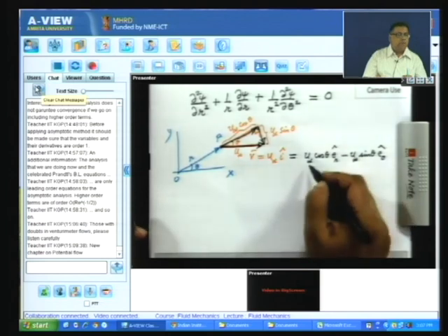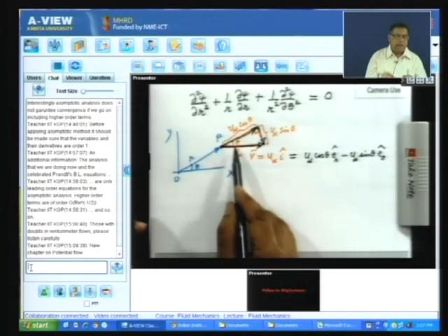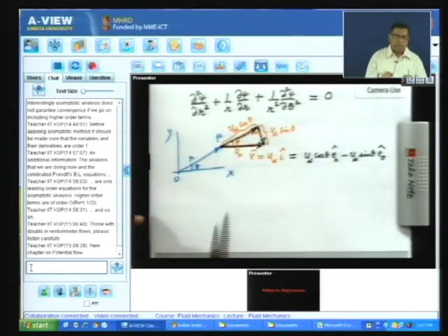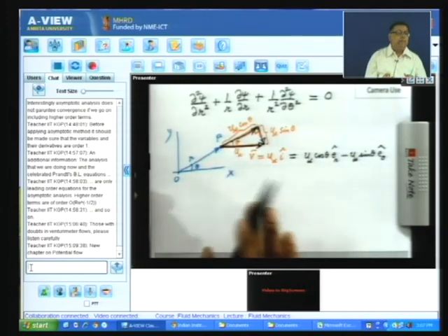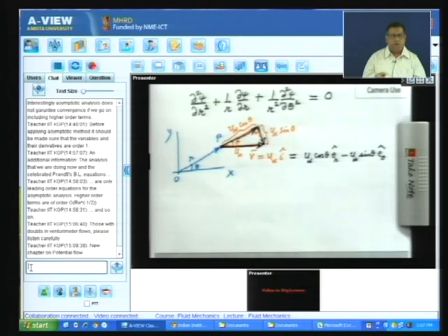So, the radial and azimuthal or swirl velocity components here will depend on the angle for the case of a uniform flow. Now, far away from the cylinder, the velocity will become uniform, because the cylinder will not affect the flow at infinity. Upstream the flow was a uniform flow, downstream and far away from the cylinder it will remain a uniform flow, since this is an inviscid flow.